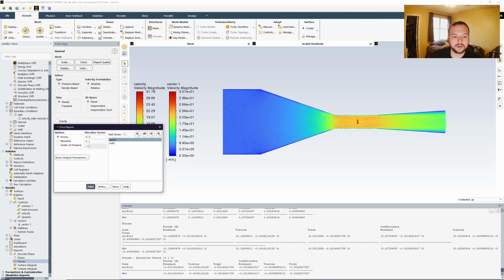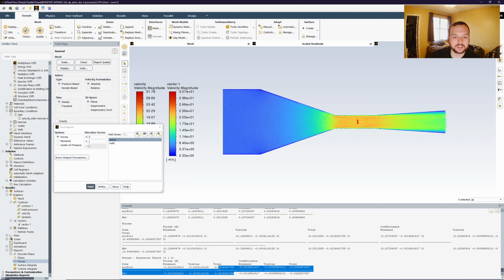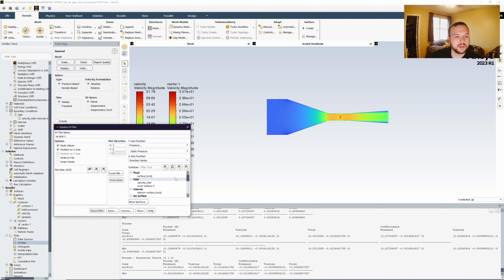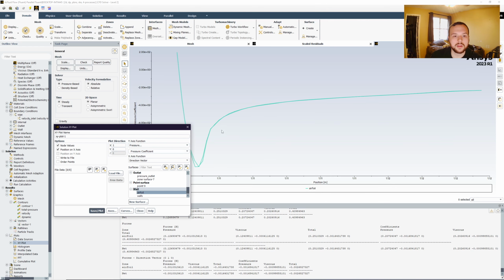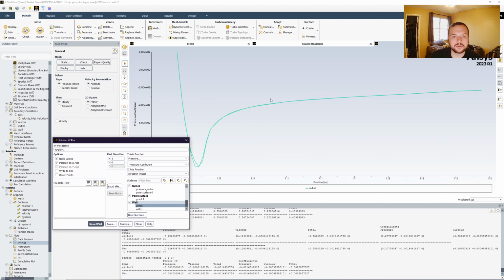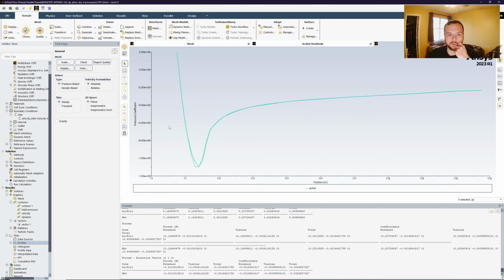and now we get totally different things. And again, you non-dimensionalize this. So then, next, you can create a plot for pressure coefficients if you choose so. And again, x equals 0, y equals 1, and we want it about the airfoil, not anything else, the airfoil. And this gives us a pressure coefficient, which again is inaccurate compared to when you actually non-dimensionalize, but this is what you get. And now you do the same thing if you wanted the coefficient of lift, except it would be x equals 0, y equals 1.